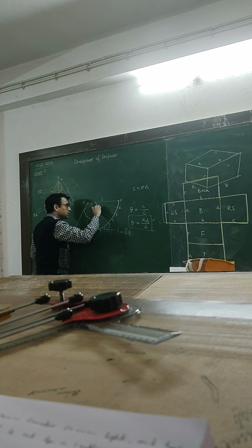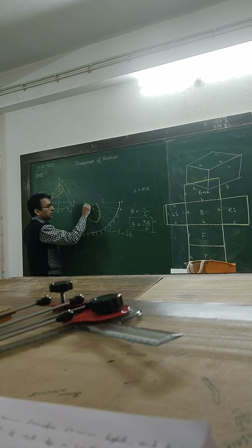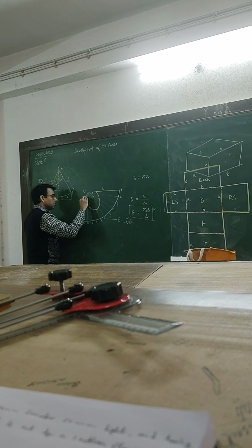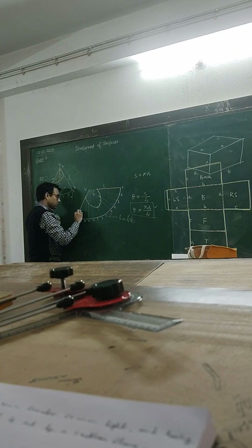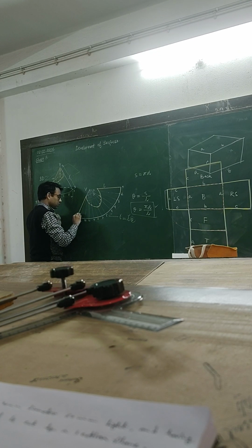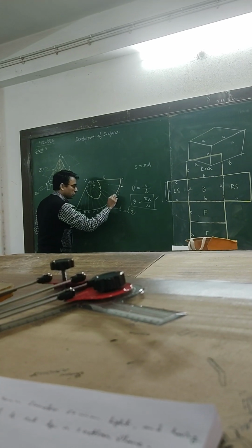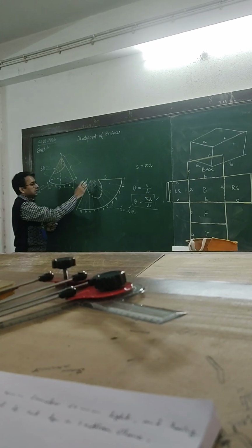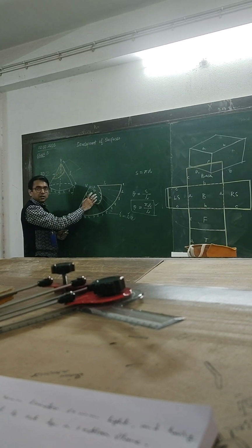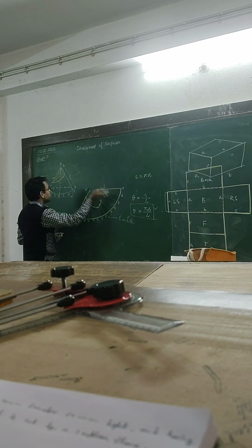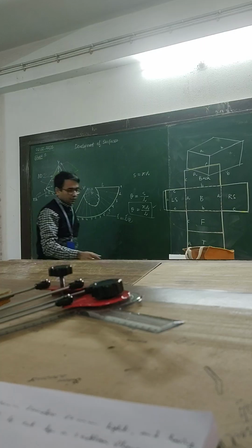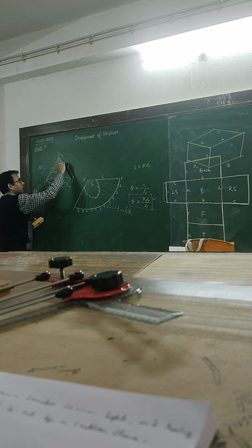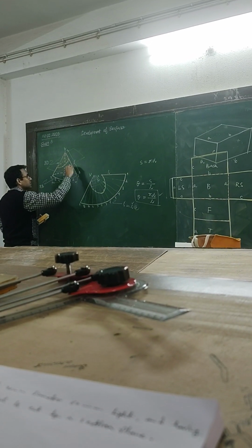It's like this. And this part will be faint lines, and the outline I can draw like this. Okay, and this part will be faint lines, construction lines. Clear? Therefore, this is the surface from which you can produce this. Which one? Only this part, the lower part. So you have basically the lower part of the conical surface.